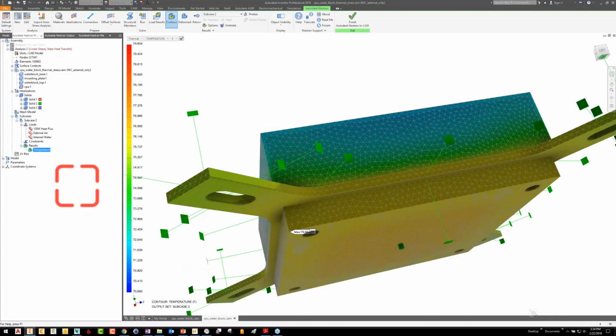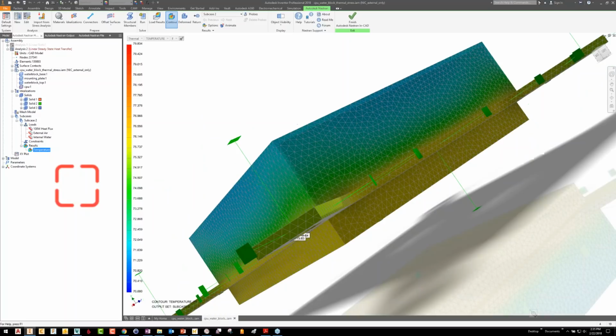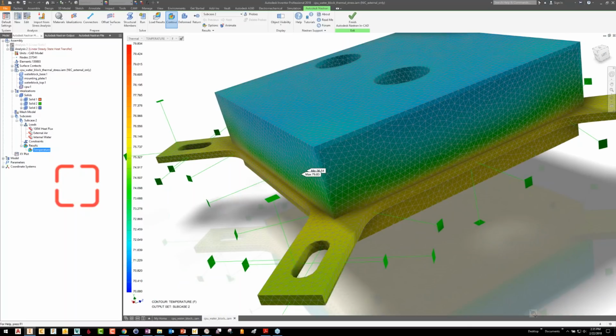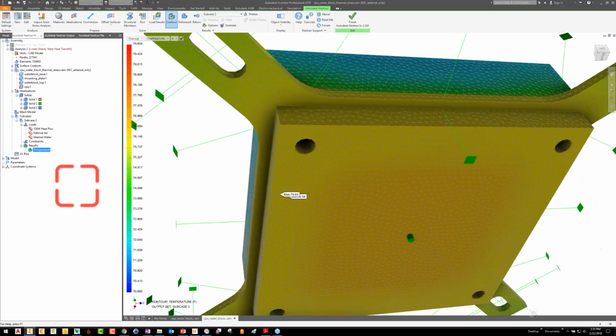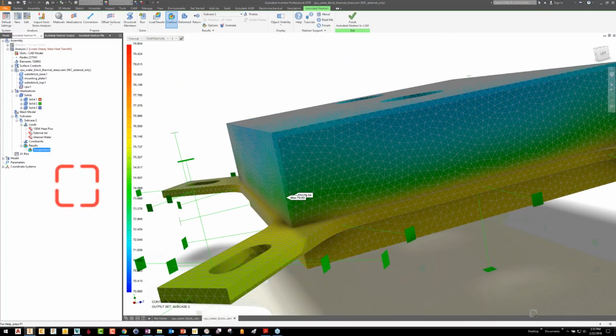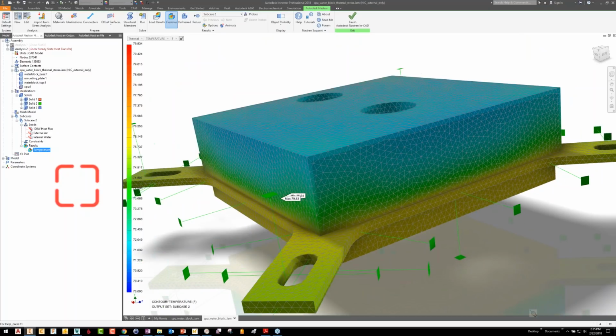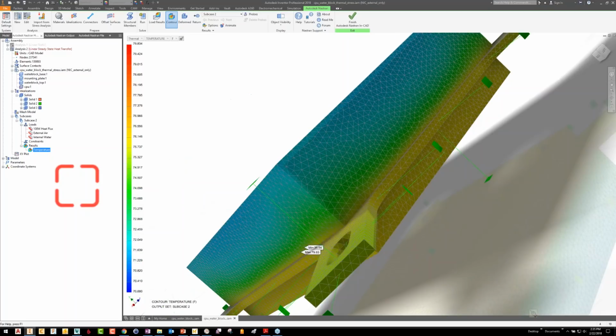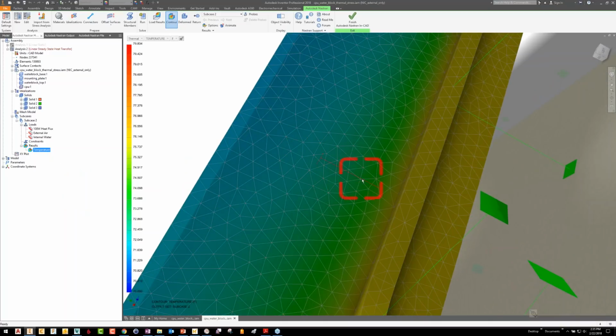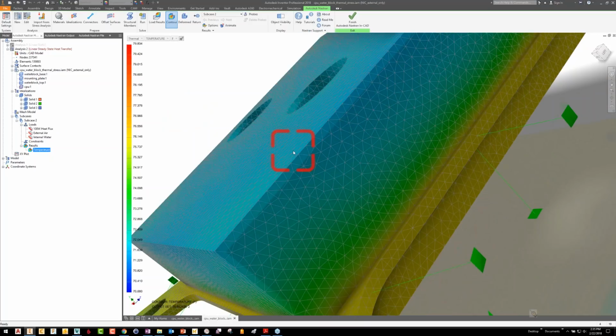So this is typical of thermal results, right? The temperature is the output. We get a temperature at each node. And we can see the hotter zones more gradually transitioning into the cooler zones. This is what you can't get in structural alone without running thermal. So you can see how mesh would come into play here. If you think about each one of these points where the elements meet up as a data point in the curve of this thermal gradient, the more points I have, the more natural the curve, the more smooth it's going to be. If I have too few points, then I basically have a jagged line that represents that gradient, and it's less accurate, it's less real life. So the more data points you give it, the better the result.